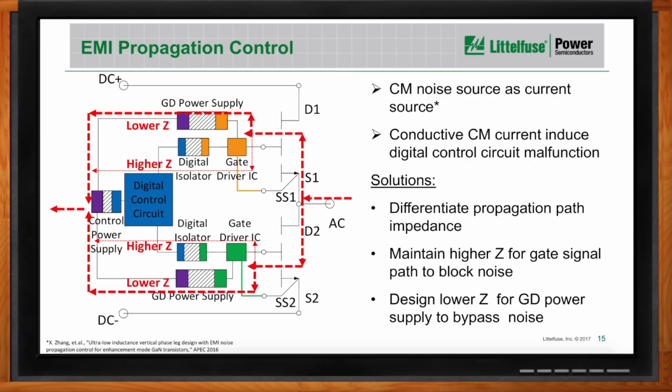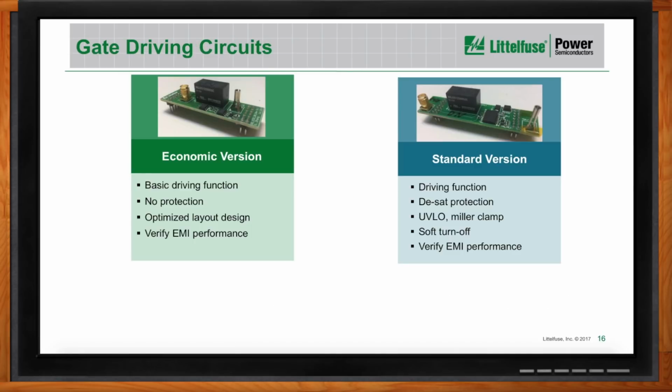Yes, to make it easy for our users to design the gate driver circuit, we will provide different gate driving solutions for different purposes. Currently, we will provide two versions of gate driver circuits. One we call the economic version, which has only the basic driving function with no protection. This one has an optimized layout design and verified EMI performance. The main purpose of releasing this version of the gate driver is to help our customers understand the driving design details for silicon carbide devices, and since this one does not have any protection features, the users still need to design their own protection features surrounding this basic driving circuit.